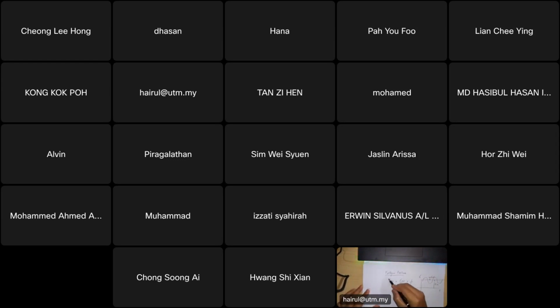So that's why the equation is like this, sigma EA over your endurance limit. Remember, in fatigue failure our strength is not SY. We have to calculate the endurance limit. As I mentioned in the previous class, the endurance limit is the modification factors times Sn prime. Sn prime comes from the RR Moore test, which is a standard test already.